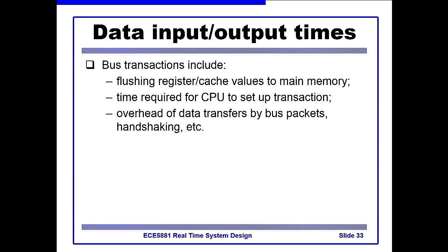All right, now most people don't think about what is actually also a side effect of this. So when we look at bus transfers or transactions, in the lab, we ask you to use a special instruction with I/O on the end of it, remember? And that was about flushing or bypassing the cache. The cache is a high-speed memory that shadows the main memory and speeds up transactions. Processor reads and writes by having a faster access time.